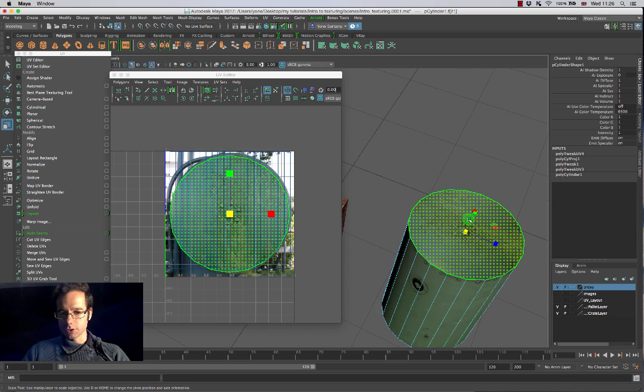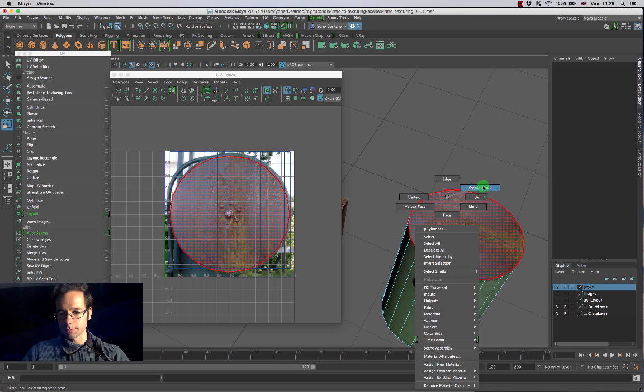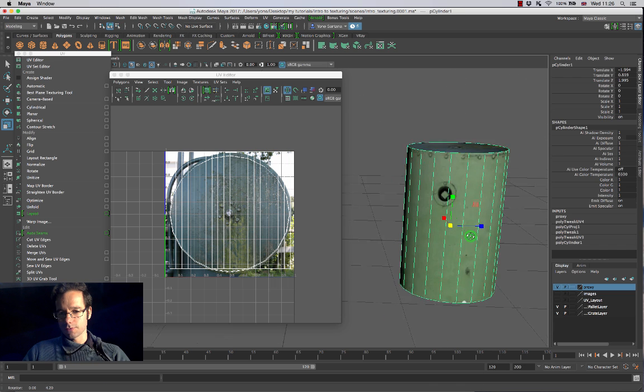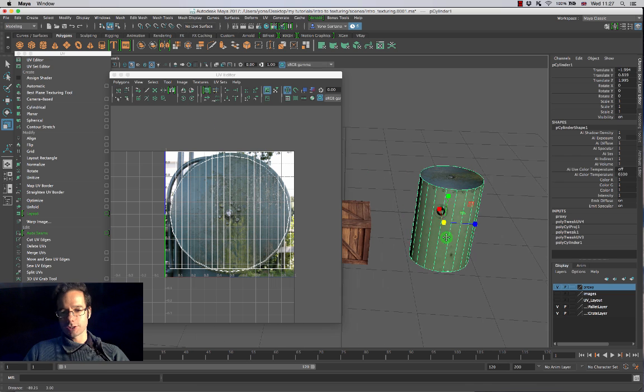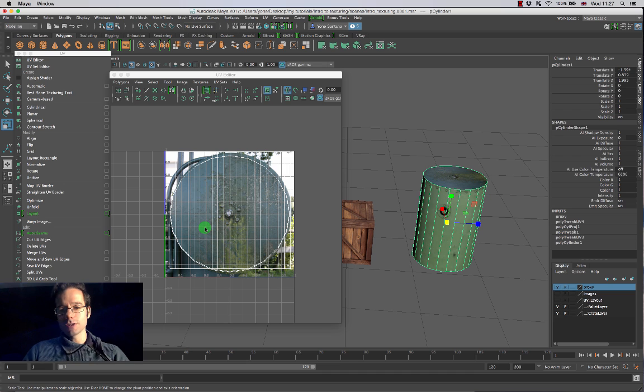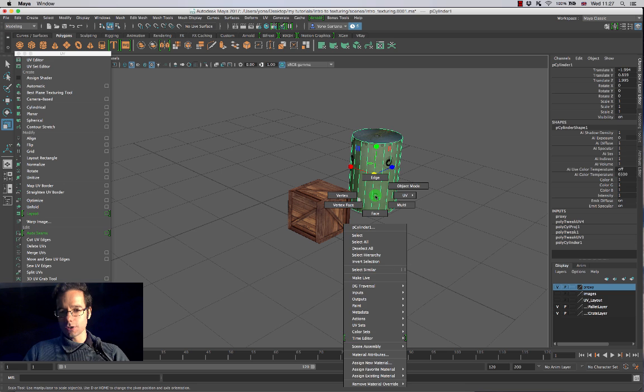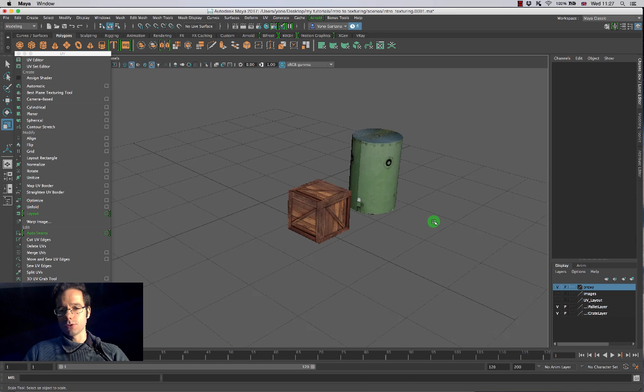Okay, so there we go. I have myself a top little texture over here, and I'm going to go into object mode, and then I'm going to look at this from the side as well. Now, this isn't what I would consider professional texturing right now. This is something that beginners sometimes should do just to start learning the tools. It's more important for me at this stage that you guys are comfortable understanding how you can select UVs and how you can move and scale and rotate them, rather than making perfect texture work at this stage.